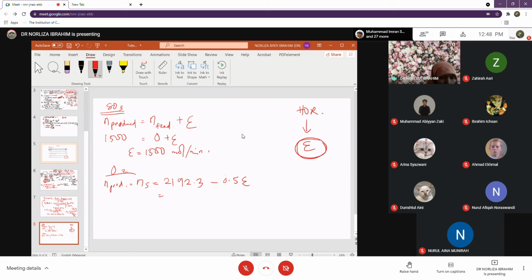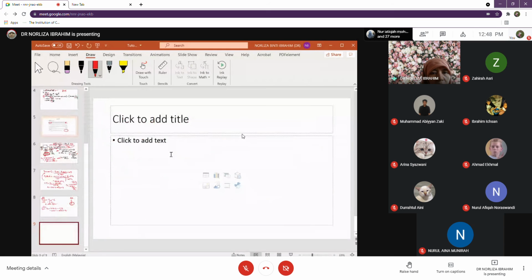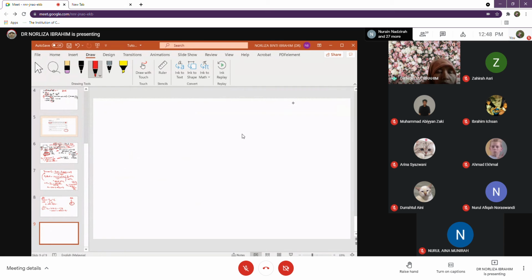So you should get 1442.3 mole per minute of oxygen. Okay, so I guess we're done with the material balance. Now you can proceed with the energy balance. For the energy balance, as per the energy balance procedure, write the equation and then solve. Then the table. So we first write the energy balance.